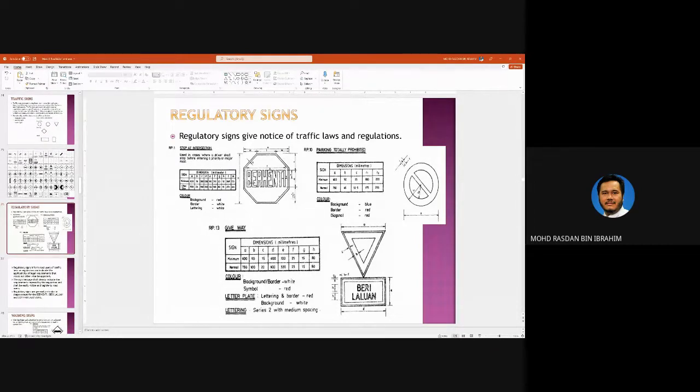And also the height. Highways have a significantly taller signboard height compared to normal roads. Federal road, for example, is different in height from local road. Okay, we have different specifications. So you need to check that and make sure that the contractors are actually adhering to the specifications.